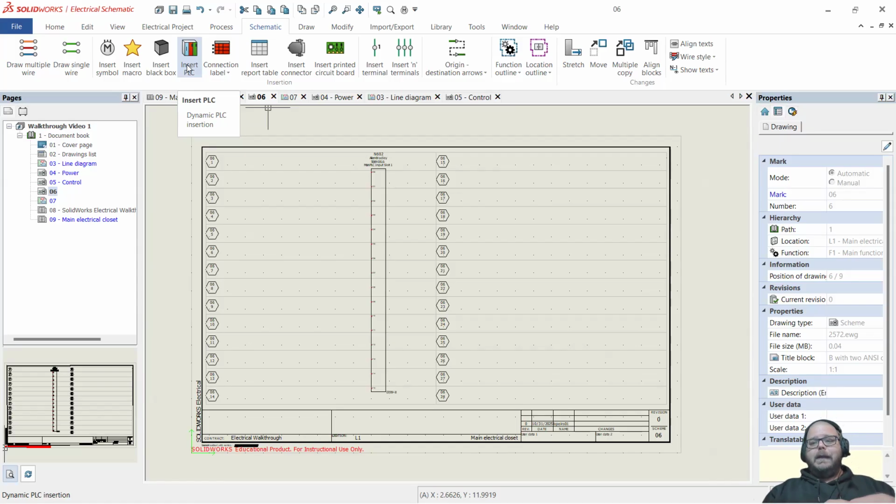But nowadays, in Studio 5000 on Allen Bradley's side and the TIA Portal on the Siemens side, we have tag names and variable names, right? We don't have direct memory addressing, and their automatic numbering doesn't really account for that. So what you end up with is auto numbering that's not really any better for documentation purposes than our normal wire numbering. So why not just stick with the normal wire numbering, right? So I don't recommend doing the insert version because it's going to sort of try to shoehorn and force you to do that automatic terminal numbering.